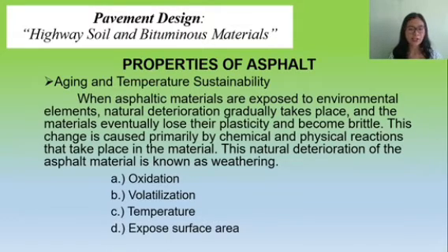This natural deterioration of the asphalt material is also known as weathering. So, for paving asphalt to act successfully as a binder, the weathering must be minimized as much as possible. The ability of an asphalt material to resist weathering is described as the durability of the material.